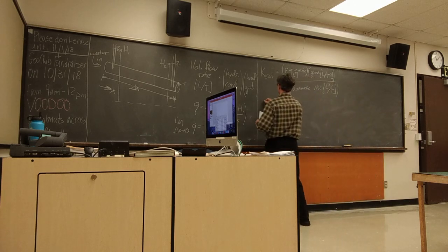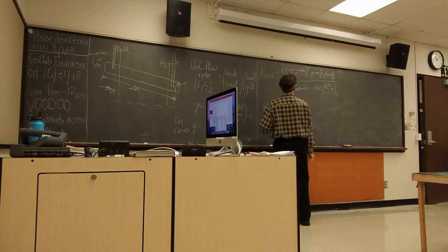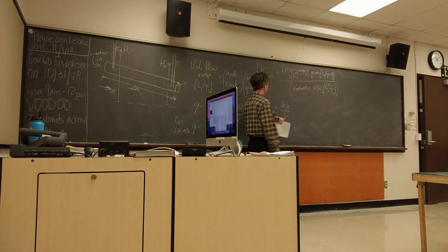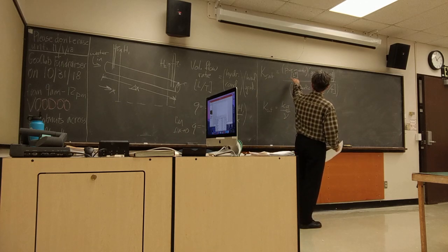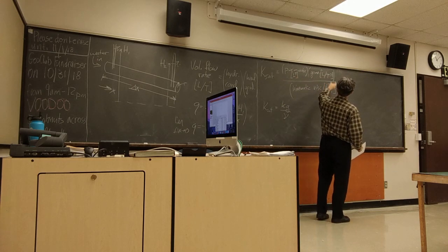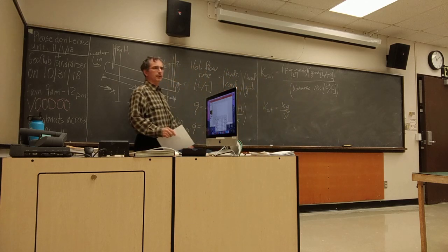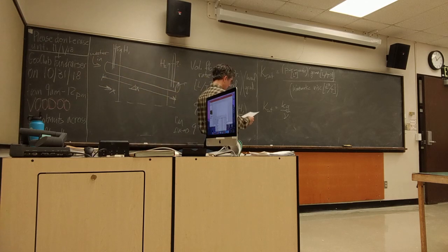So typically we use a little k for permeability, and nu, lowercase Greek letter nu, for kinematic viscosity. Let's just make sure the units are working out right. L squareds cancel. One of the T's cancel, length per time. Yes, so hydraulic conductivity should have units of length per time. Does rho come into play at all in this?